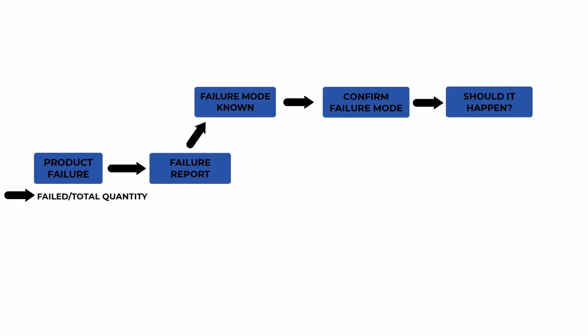The result of our analysis should be a clear problem statement. For example, the failure on the 3D printer that resulted with the printing head colliding with the print bed was due to the distance sensor being mounted too high during the assembly process.